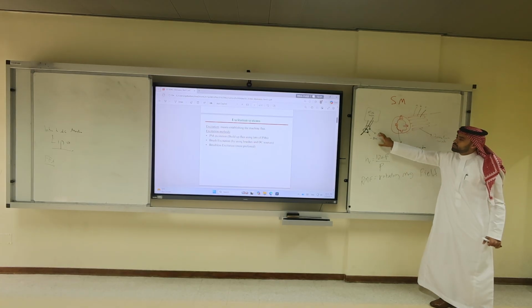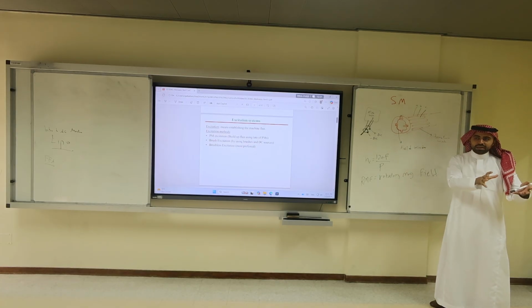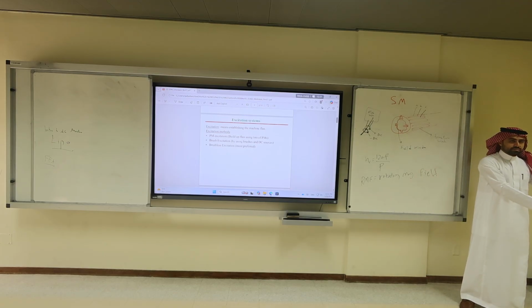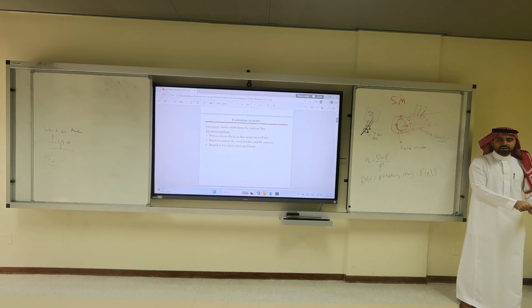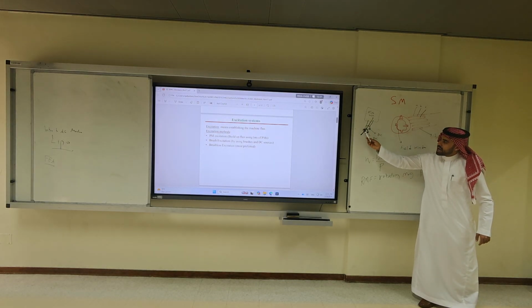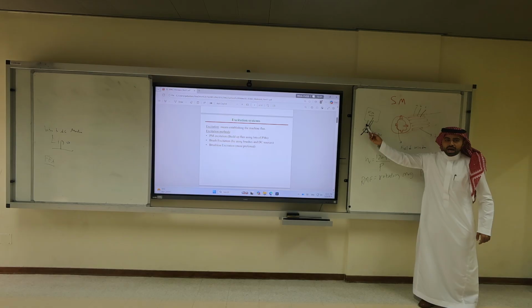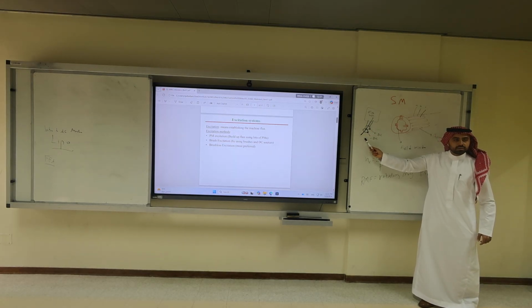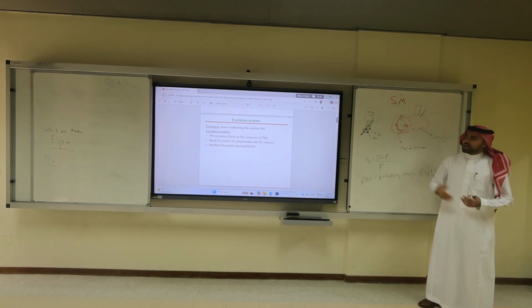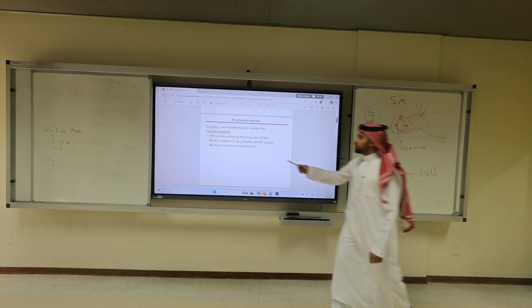And here you can have your DC source, maybe a small battery, or for a big generator, a small DC power generator. Same as what we see in the lab. But the problem is the shaft rotates all the time, the slip rings rotate all the time, the brushes need to be replaced from time to time. So this solution is affordable and cheap, but it's not durable.